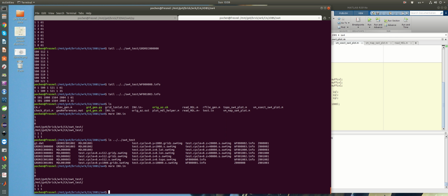If I increase this number to above 1, say 2, then SW4 is going to do wave propagation simulations. It's going to skip creating those mesh files and model files. It's just going to do straightforward wave propagation simulation to create those strain fields as 4-dimensional volumes and store those strain fields into this particular directory.